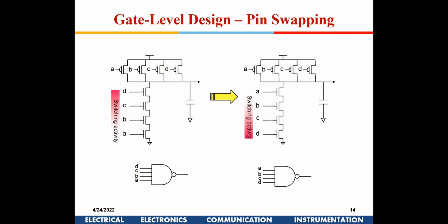for low power consumption, to target reducing of power consumption. Is this okay with all of you? Why have I kept this low activity cycle here, right? Because again this is a 4 input NAND, right? So this output has to go low only when all of them are 1.